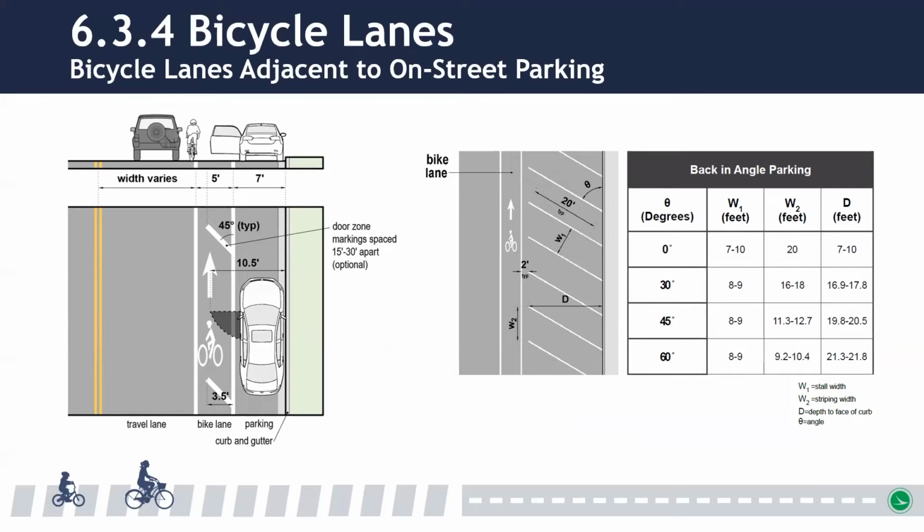When a separated bicycle lane is not feasible or an interim solution is needed, a buffered bike lane should be provided, which can position bicyclists outside of the door zone. The guide provides steps a designer should take in order to rebalance the roadway to provide the preferred facility type and what to do after all options have been exhausted.